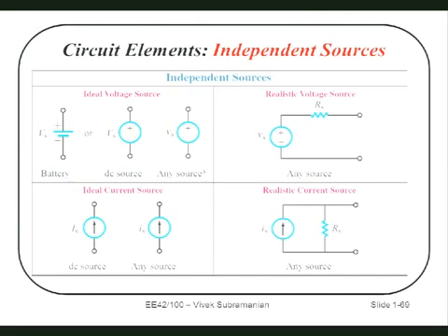If I put a 0-ohm resistor across it, how much should flow? Infinite current. That battery didn't work that way, right? That battery started topping out at about 100 milliamps or so. So that's not a perfect battery. Real voltage sources are always actually this: a battery with a resistor in series. And that resistor value is usually pretty low, so for normal situations, we can ignore it. But when you do something dumb, like put it on a very low resistance like my tongue, or with an ammeter going directly across it, that resistance matters.